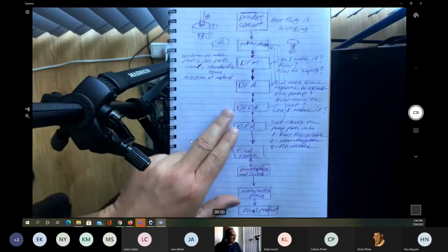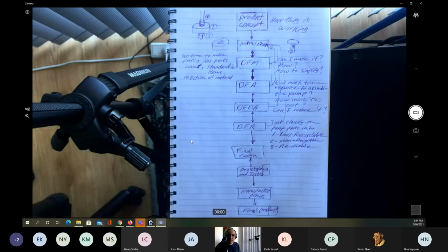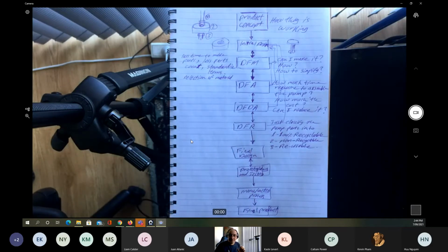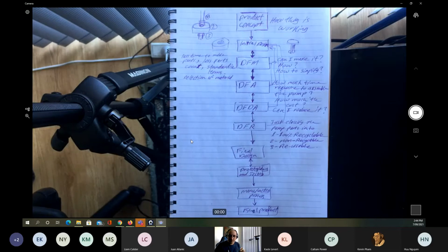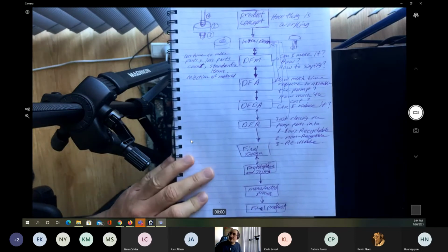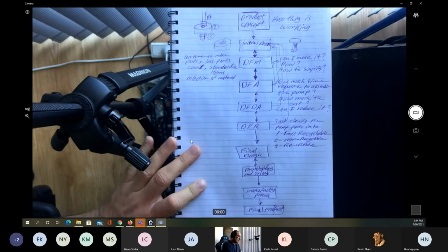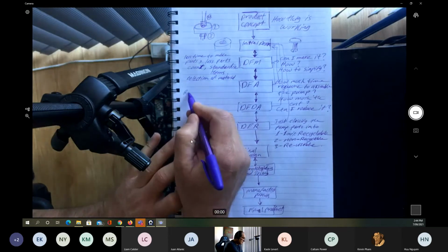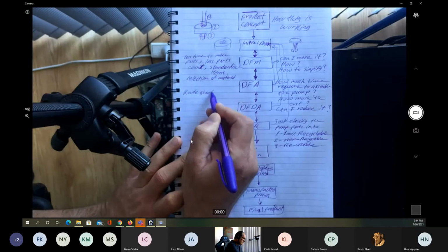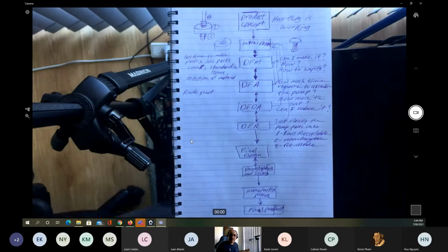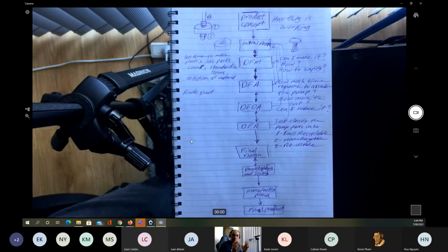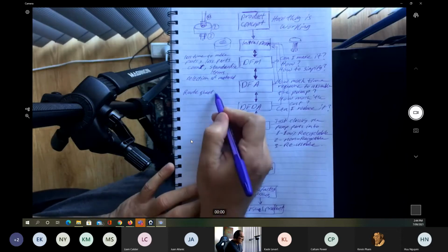During that, for the design for the manufacturing, you need to write down what we call the route sheet for every part. Now, the route sheet, if you remember from the casting operation, is how to make the part, the machine process of the part. Okay, how to make the thing in steps.